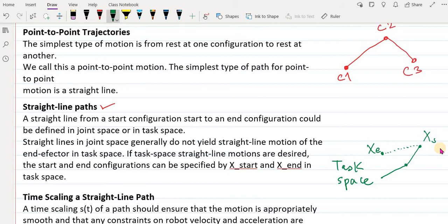It may have a different kind of curve. There in your configuration space you can do the motion planning, path planning, and when you follow this trajectory in your configuration space, it will eventually translate into a linear straight line path in your task space or workspace.